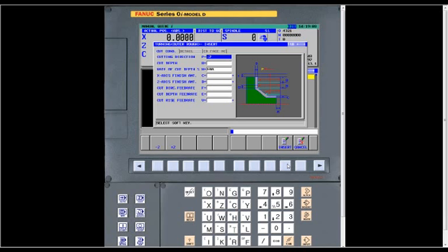Whenever you put information into it, like here, we'll just go Z, Z minus, then it's asking for a cut depth. And you can see it highlights Q, so that it's the depth of cut per side. This is a radial amount. It's very important that you remember that. It's a radial amount.